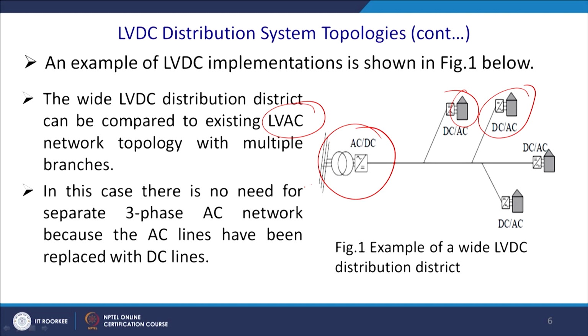One of the advantages is that the power handling capability of the DC is more, because of the skin effect. Generally once you have a skin effect you have harmonics, as I was saying, and if you have a sufficient amount of harmonics, you require to derate your converter, your cables, and your transformer. For this reason this aspect does not arise when you have direct DC transmission.